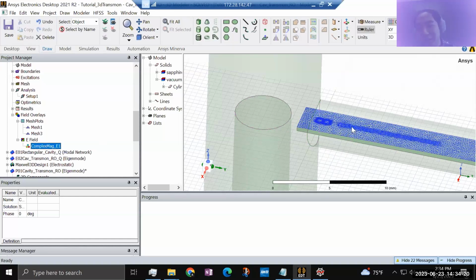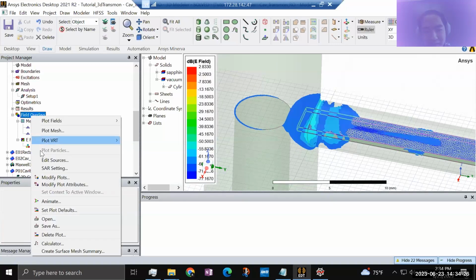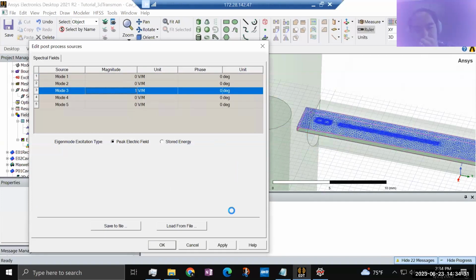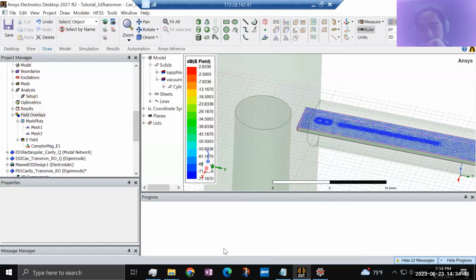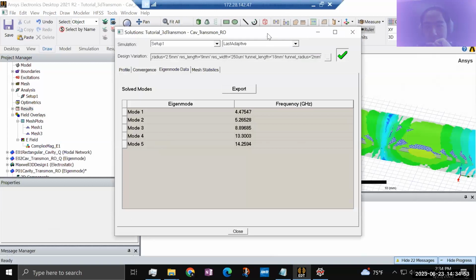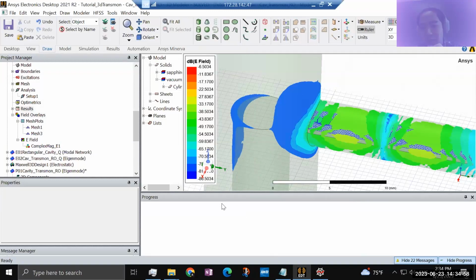Of course, when you make the design, you should have a rough idea of what frequencies you want these modes to be. So now if we plot that field structure for the third mode, that I expect to be this readout mode, which should have a structure of lambda over 2, which is E field strongest on these two ends. And that looks like this. So just to confirm, the third mode is the readout mode that I targeted at around 9 gigahertz, which is from this on-chip strip line.